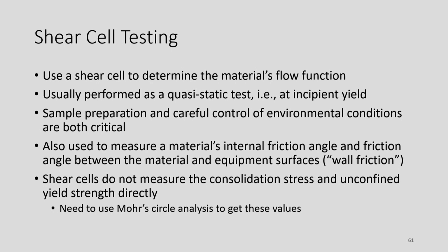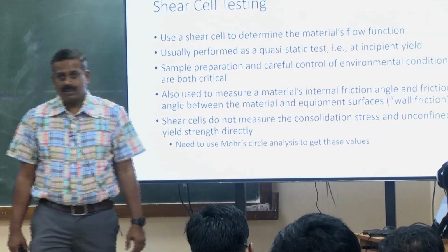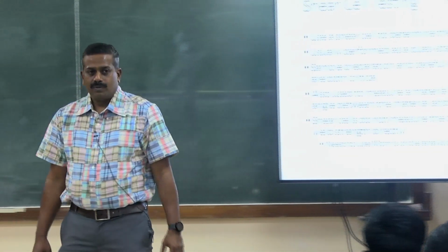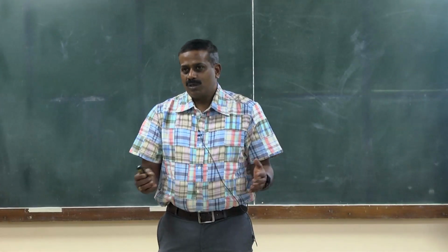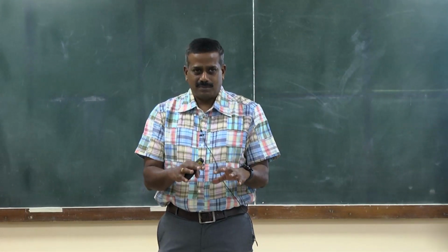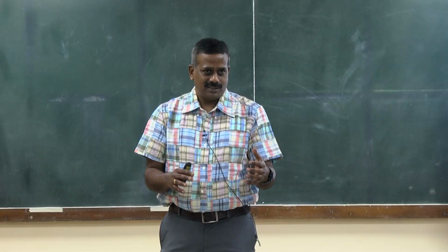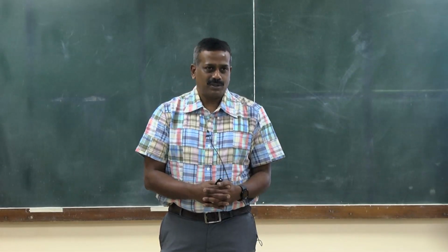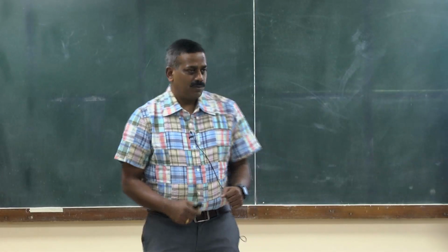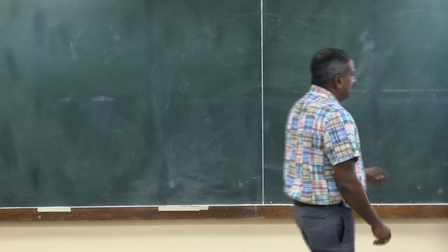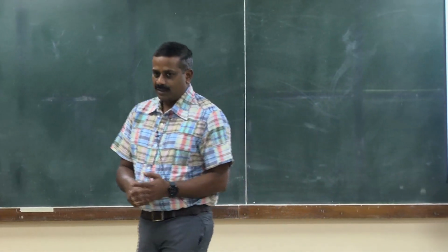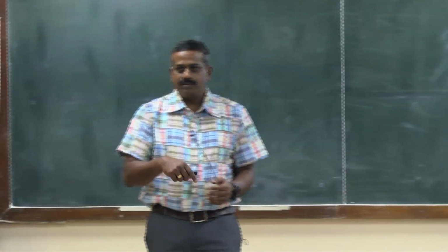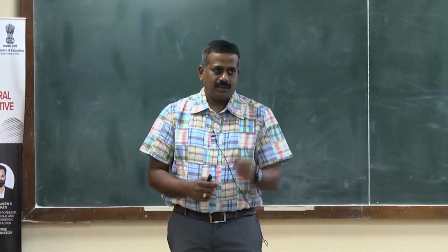And as we talked about environmental conditions, sample preparation is also very important. When you pour powder into a sample cell, you don't want to unknowingly consolidate it, right? Then you are adding extra, artificial strength to the powder. For most instruments, you have to pour the powder through a sieve for shear cell testing, so that it fills uniformly within the shear cell, the cup or the holder.